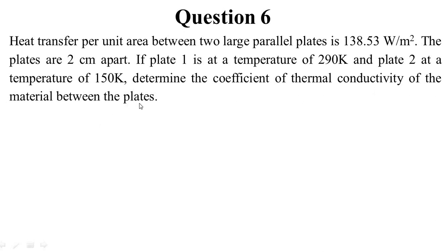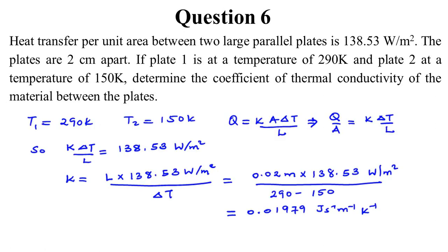So we are talking about the rate of heat transfer given by the formula Q equals K A delta T over L. L is the separation between the plates, and delta T is the change in temperature. Heat transfer can only be possible if there's a temperature gradient. So there's a hot point and a cold point, and heat will transfer from the hot region to the cold region.